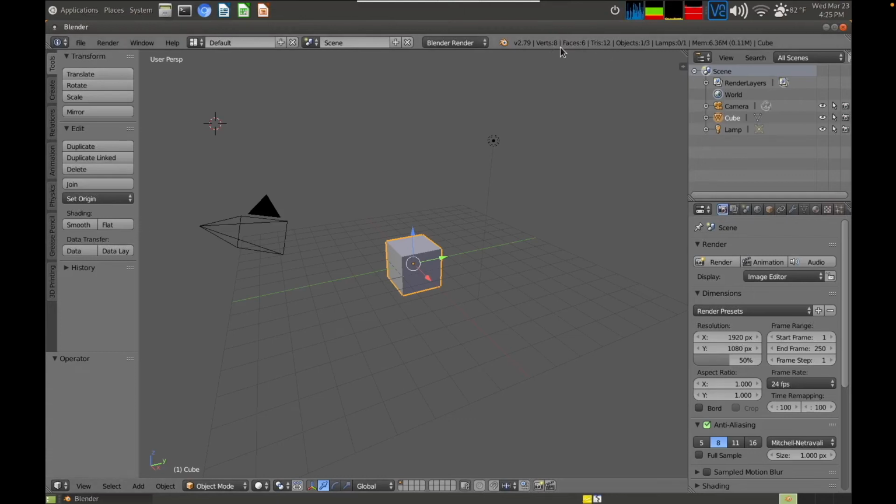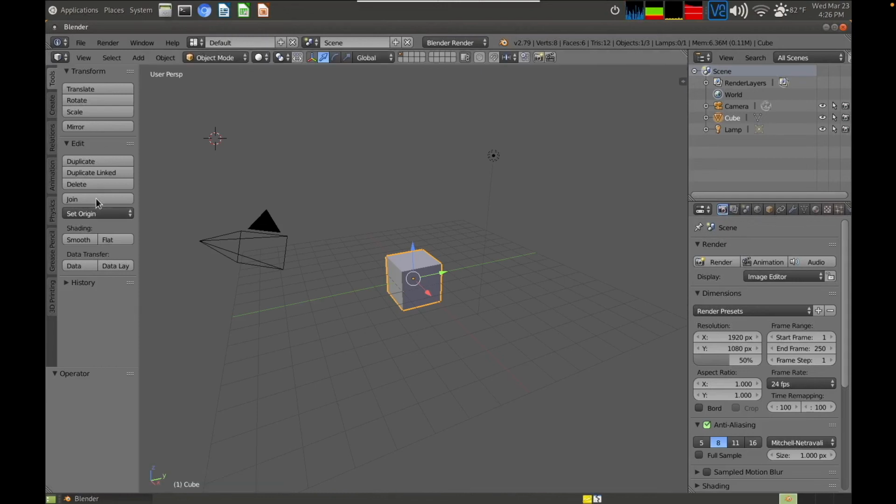Okay, so the next thing I'm going to do is actually move this menu bar for the 3D viewport editor at the top, because it'll be a little bit easier to work with if it's at the top. So you're not looking down all the time to get to those menus. It's actually how it's set up in newer versions of Blender. So you can right click on the header for this editor and you can click on flip to top, okay? So now you don't have to look down there anymore to get to any of the menu functions or any of the buttons.